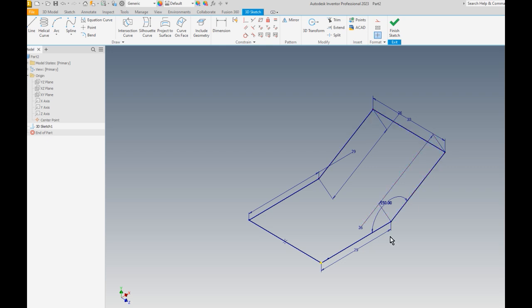The biggest blend that I do want to have is basically, I want to put fillets. Okay, fillets in 3D Sketch in all software have different names. SolidWorks uses the typical fillet, which is okay. Solid Edge also uses the same concepts within the aspects of 3D sketching. Inventor perceives that within a 3D sketch, it almost thinks that the line is a cube or some sort of a wire. So if that's the situation, the nomenclature is a little different. So we're not looking for fillet, we're actually looking for something called bend.